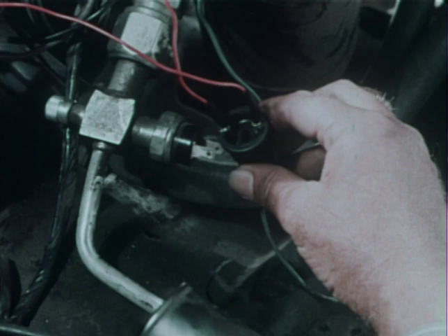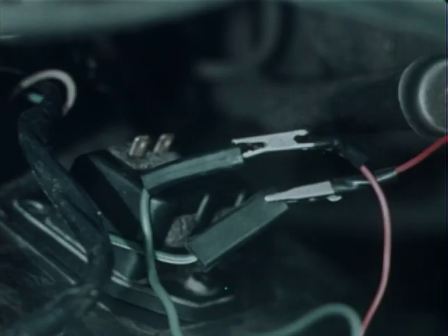The technician next checks the compressor discharge pressure switch by attaching a jumper wire across the terminals of the switch connector. If the clutch engages, the switch is defective, or the system is low on refrigerant. To determine if the system is in need of charging, the refrigerant quick check procedure can be used with the jumper wire still in place. In this case, the clutch did not engage when the switch was jumpered across, indicating that the malfunction is somewhere else. The technician continues his diagnosis.